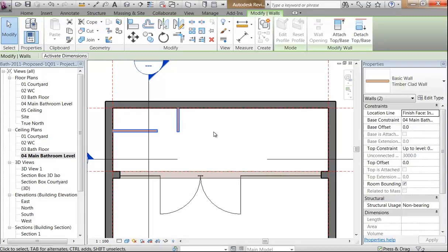Sounds crazy, but it's the most logical way of doing it. Until you do it, it won't make sense. But once you do it, you'll see it actually is the simplest way of doing it. So that's why it's called a reflected ceiling plan, because it's like you've got a mirror on your floor and you're seeing reflected on your floor whatever's on your ceiling. Right? And the reason it's simpler to draw is because you don't have to flip it over. You're not drawing a mirror image. You're drawing it the same way your floor plan faces, but instead of drawing whatever's on your floor, you just draw what's on your ceiling. It's actually much simpler to draw, even though it's more difficult to explain. It's simpler to draw because you don't have to draw the walls.